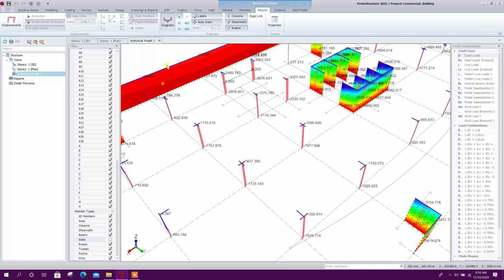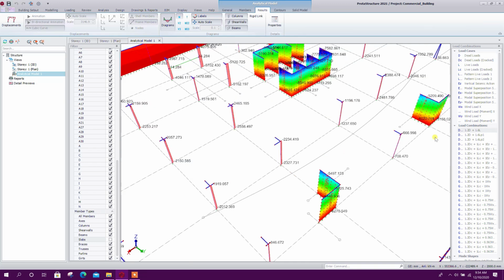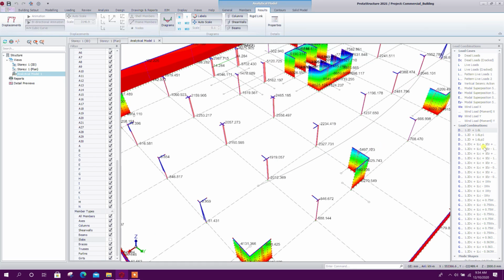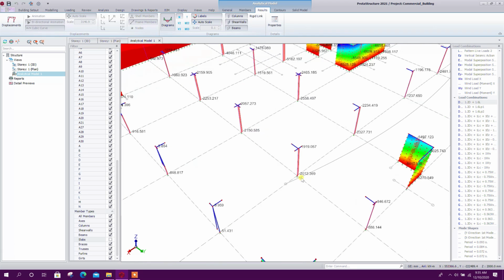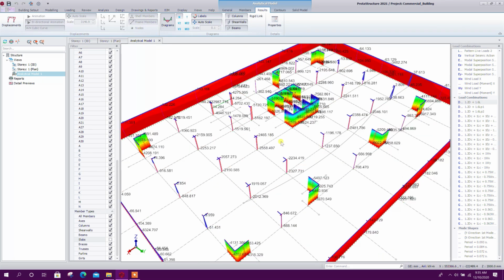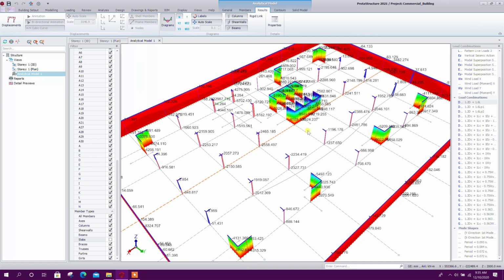Here we can see the axial load. In the analysis, if we choose non-factored dead load and live load result, then here the DL plus LL load combination will come to show our reaction load. So in this way we can review our result. We can close this tab.